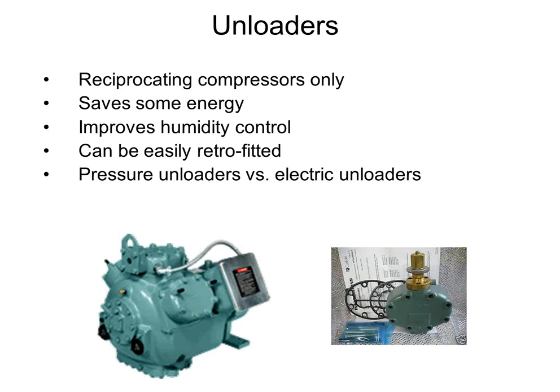So if you've got a 6-cylinder compressor, you can drop off 1/3 of the capacity with the unloader, and then you could drop off 2/3 of the capacity. Or you can shut it all the way off. You can make one compressor basically into a 3-stage compressor. So with a one-compressor machine, you can easily have 3 stages. A 2-compressor machine can easily be 6 stages. And then I've got lots of capacity control.